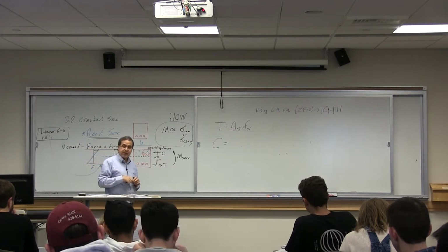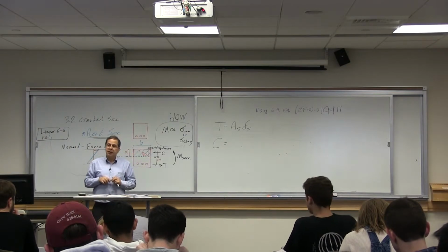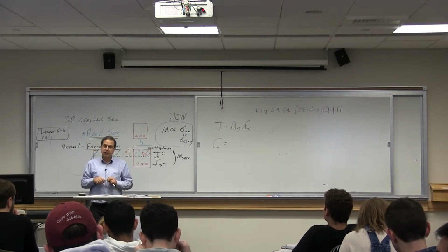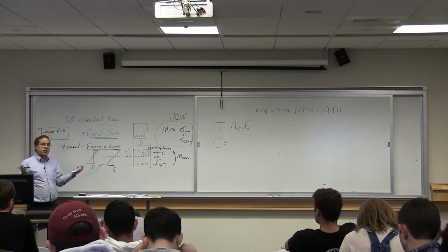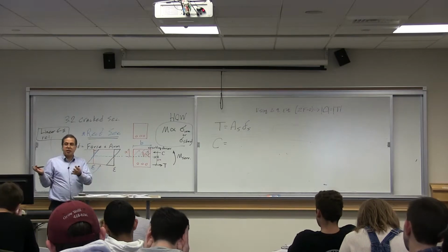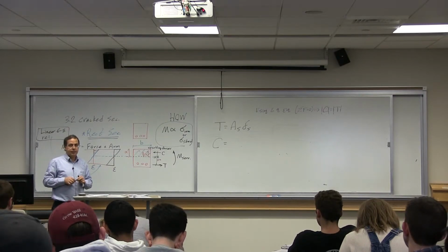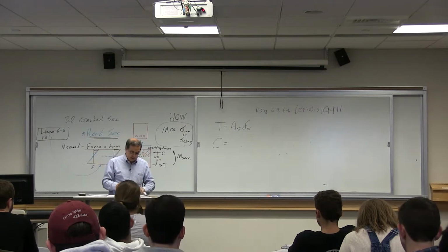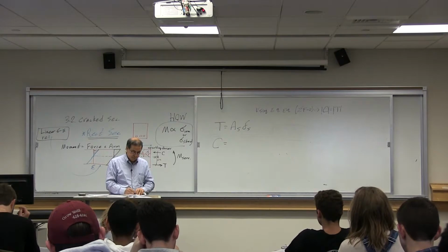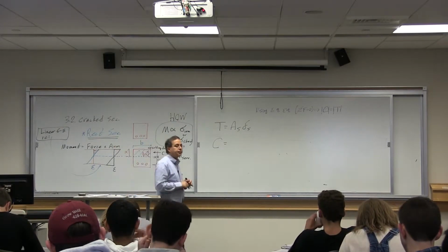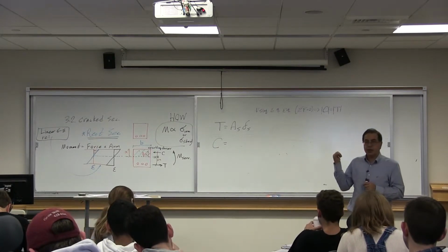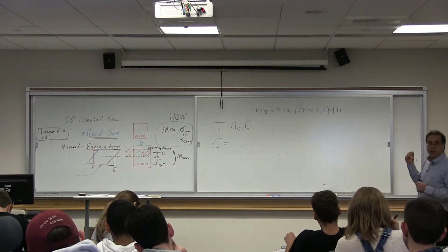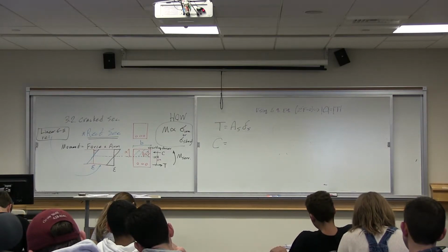Is the stress in concrete constant? It is not; we see the stress changing. If the stress was constant, stress times area would give you the force. Now that it's not constant, what's the answer? You have to integrate the stress over the area, the same way that we discussed in terms of the centroid. And if you integrate, what would be the outcome?